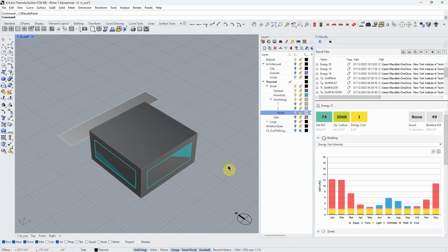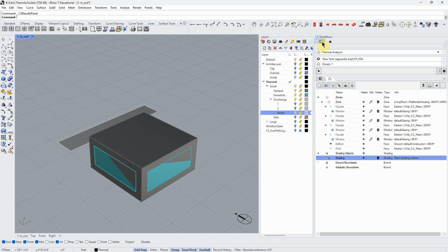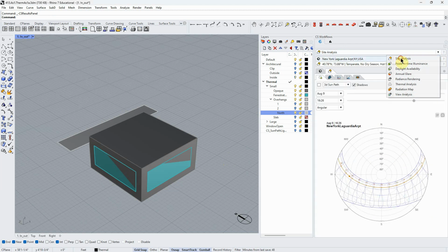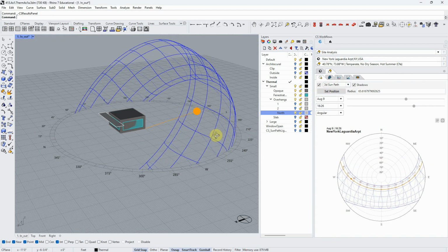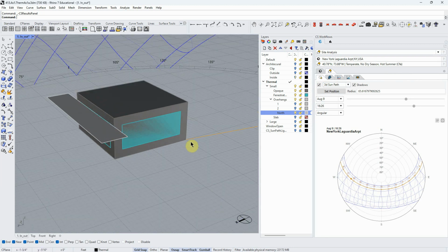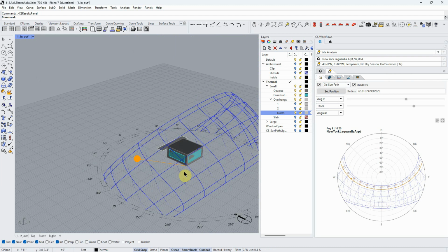So what we know in terms of our analog looking at the sun in site analysis in that situation bore out correctly in our more detailed simulation. So that's the other thing, is you want to always be checking these simulations, seeing if they make sense to you. If they don't, go figure out why and either fix something or learn something.